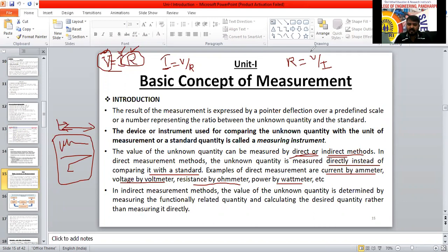By connecting a voltmeter, you can measure the voltage. By connecting the ammeter, you can measure the current here. If these two are the known quantities and we know the formula, by calculating, we will get the resistance value here. So we have calculated the resistance value.